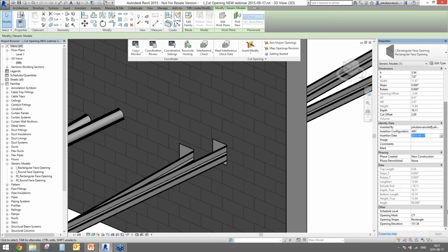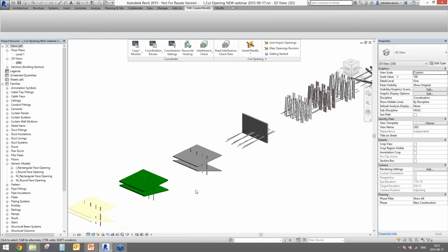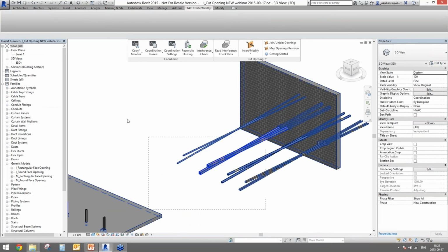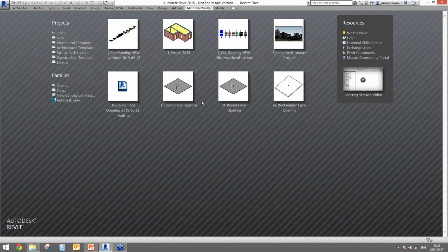If you scroll down, you will find the opening marking, like if I have the cable tray, the marking is CT. We have the opening shape, as well as the opening elevation. So this is how the cut opening could work with all structural elements. So I had 4 different MEP elements, and I had all structural elements that are supported by our solution.